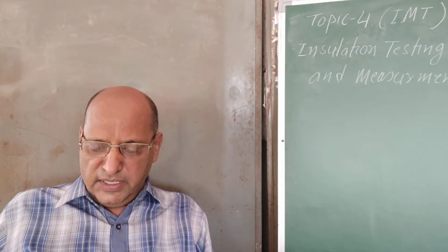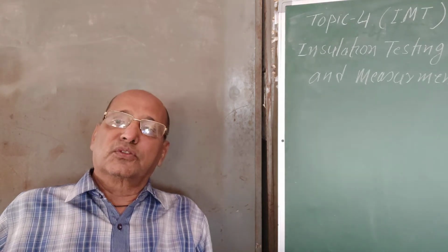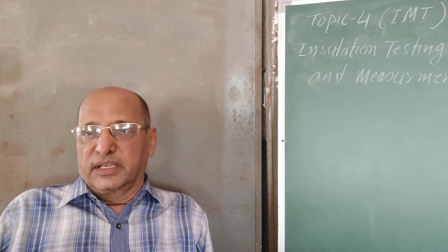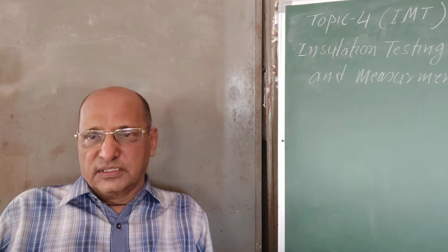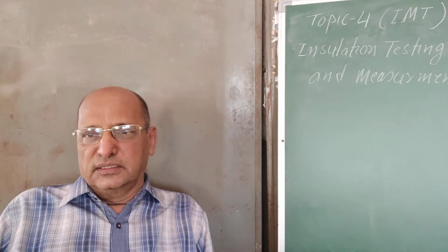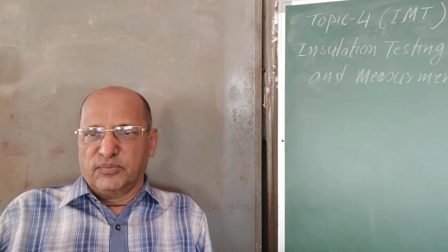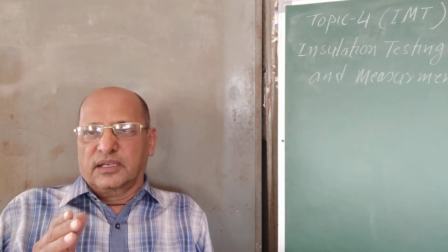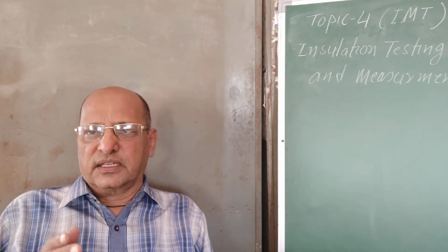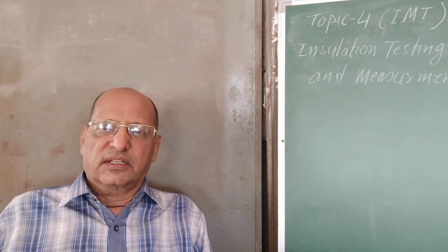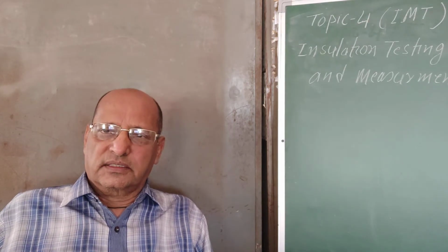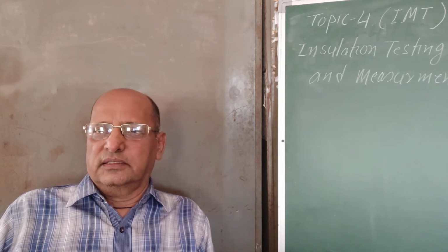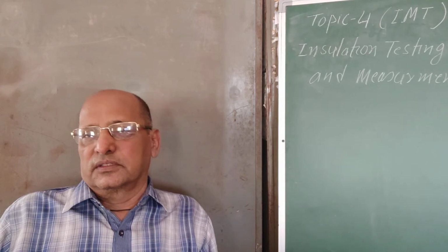So the main reasons for deterioration of insulation, as I have told you: thermal stress is one reason, mechanical stress is the second reason, and corrosion is the third reason, that is, contact with chemical gases or chemicals attacking the cable, in those industries where chemical plants are there and chemical gases are produced, like oxides of sulfur, or other acids like hydrochloric acid or sulfuric acid.